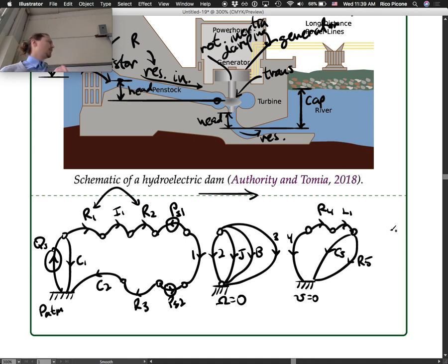The reason that I'm putting a resistor in parallel there is that your battery is going to, just like the capacitor you guys modeled in, I think, your last homework, have some leakage. So you're not going to be able to store this in a capacitor indefinitely. Also, you're going to deliver to a load too.